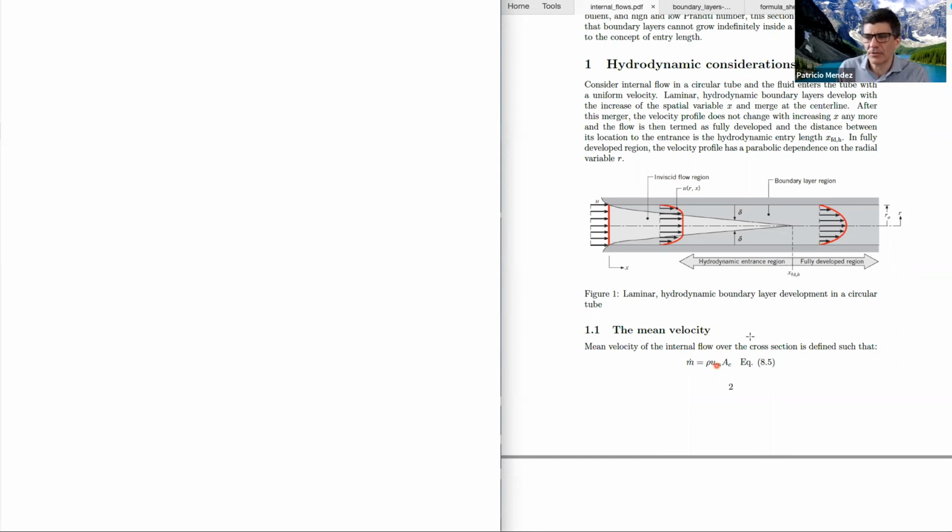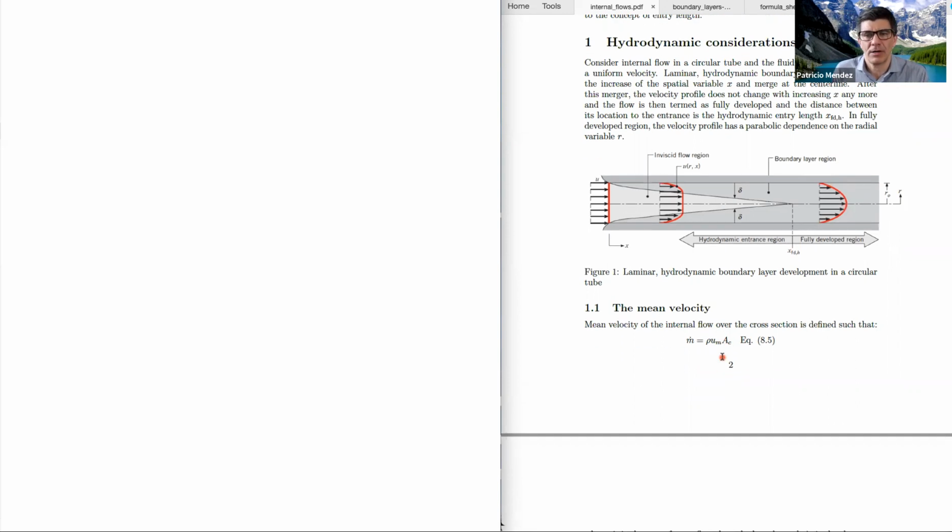Because there's a zero velocity on the surface, it's a maximum velocity in the center, but in the end, the one that helps us make sense out of things, every time we talked about previous problems in this class, in which I was coy and I didn't make any nuance, every time we said so many cubic meters per second or so many kilograms per second, we translated that into a velocity. But it's more subtle than that, right? Because we have a velocity range. So these velocities we're talking about, and the ones I've been talking about before, were this mean velocity, this average velocity.